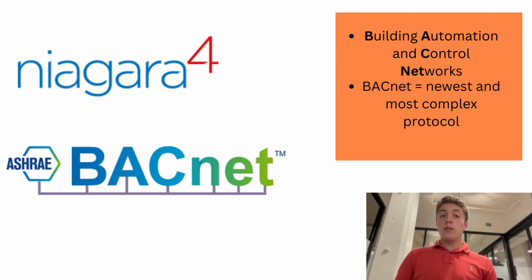Additionally, some of these other protocols only work on one brand or set of devices. They're not interoperable between all devices. However, BACnet is able to communicate across nearly all devices, which is only facilitated by Niagara. Therefore, almost all devices are BACnet compatible. For example, Honeywell, a major producer of HVAC hardware and components, makes all their products with a BACnet MSTP port, which I'll talk a little bit more about later on.